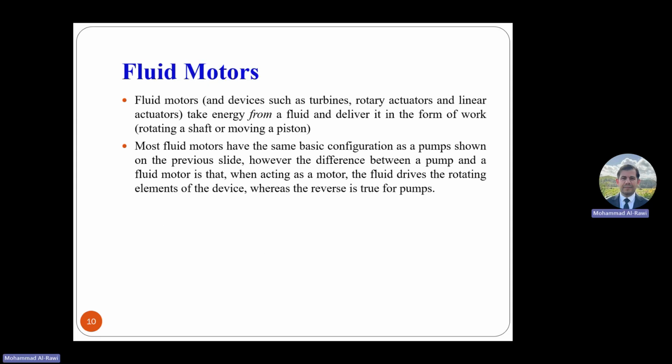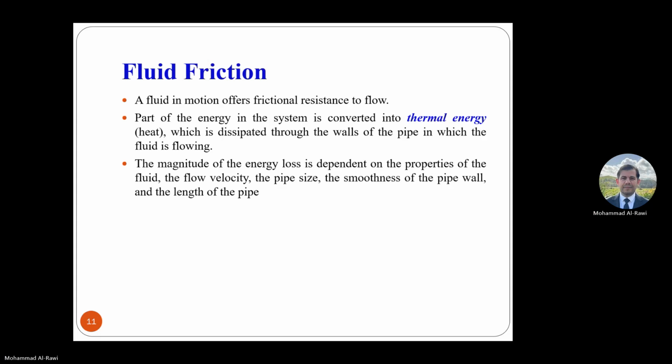Fluid motors, such as turbines and rotary actuators, take the energy the pump is delivering and convert it to mechanical energy, which can later be transferred. This is an energy loss from the system. Most fluid motors have the same basic configuration as the pumps shown in the previous slides. However, when acting as a motor, the fluid drives the rotating elements of the device, whereas the reverse is true for pumps.